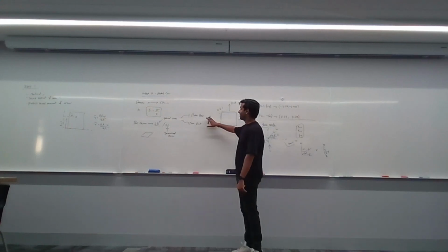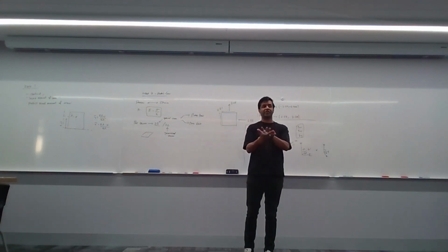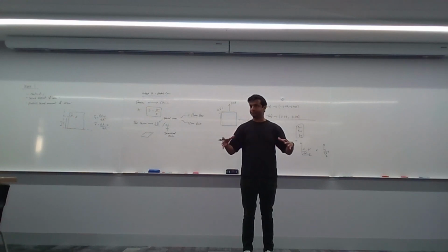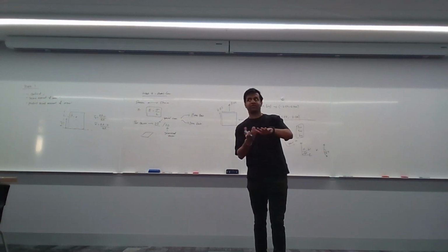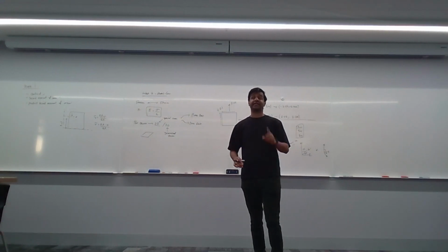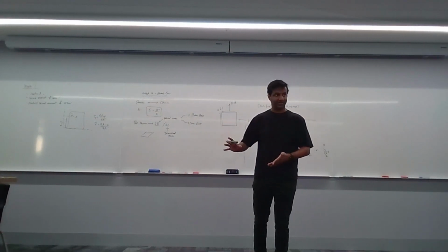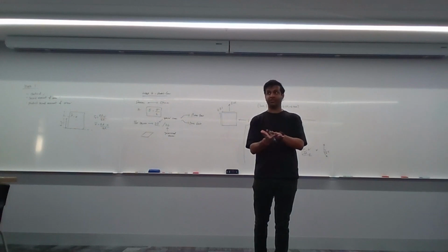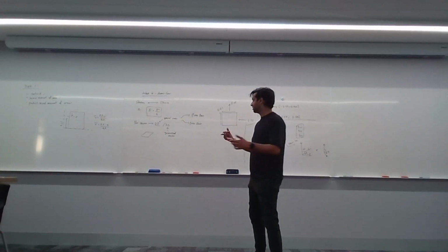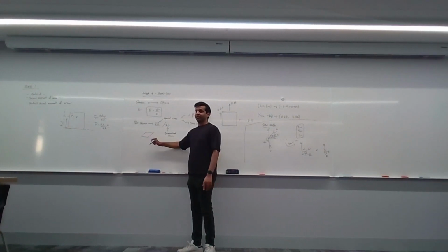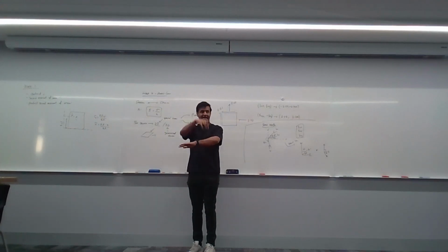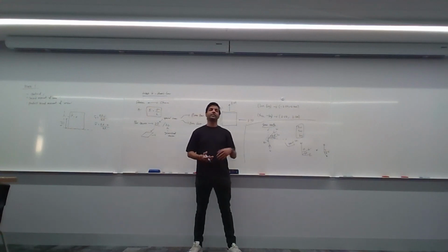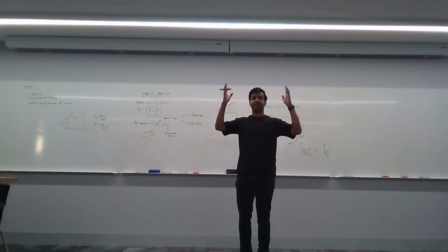That's the point. Now, plane stress means that your stresses are only applied on a plane. That means you only have stresses in, say, the x and y direction, but you don't have any z stresses. That does not mean that your strains are only in two directions as well. It just means that your stresses are in two dimensions. It can strain in however many dimensions it wants. So for example, if you've got a plate that's just sitting on the floor and you're pulling it this way and you're pushing it that way, but there is no out of plane action, that is a plane stress case. Another example of a plane stress case would be a column in a building, right?